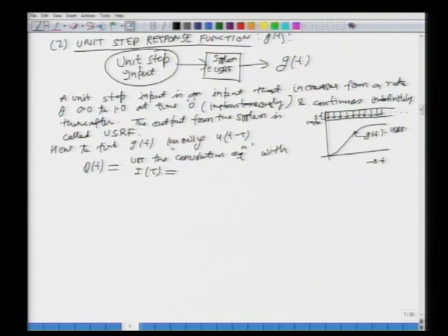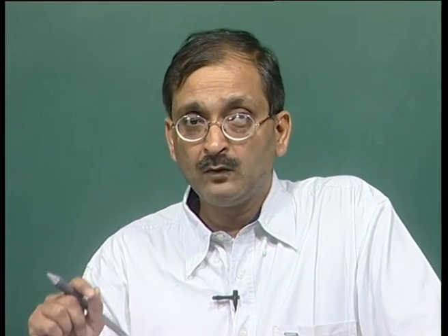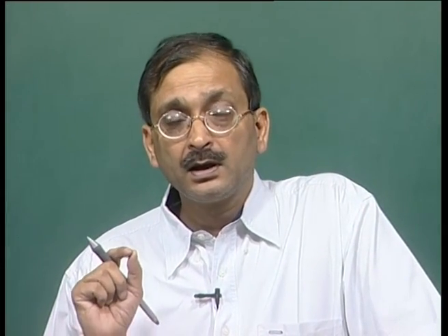And what is the rate of rainfall here? It is 1, or unity. Or I(τ) dτ is equal to 1, which is 1 centimeter per hour. So, you see that to calculate the unit step response from the catchment, when it is subjected to a rate of 0 to 1 occurring indefinitely, you use the convolution equation and you put intensity equal to 1.